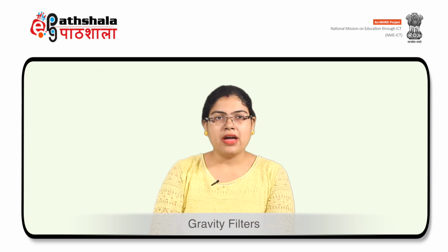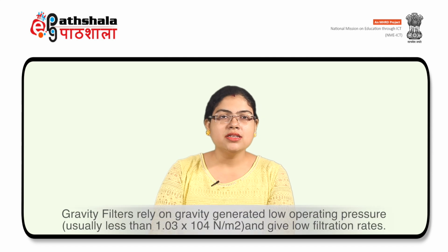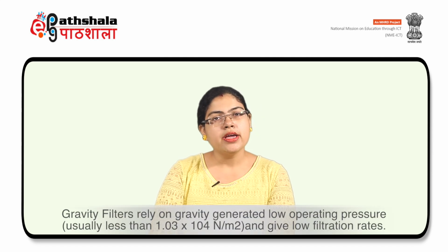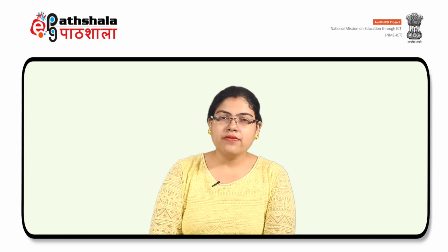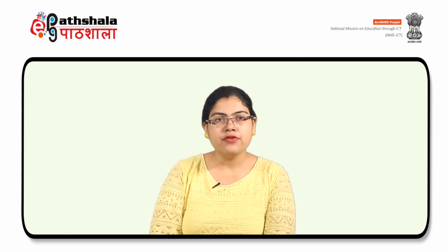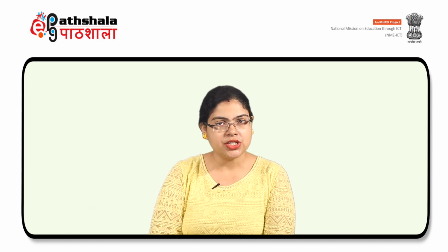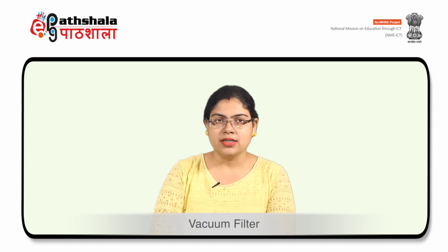Now first come to gravity filters. Gravity filters rely on the gravity generated low operating pressure and give low filtration rates. However, these are simple and cheap and are frequently used in laboratory filtration where volumes are small and low filtration rate is relatively insignificant.